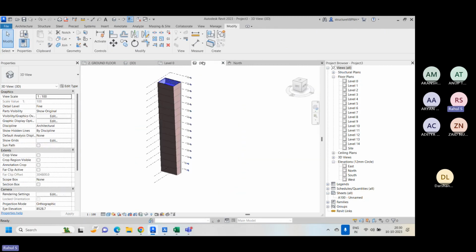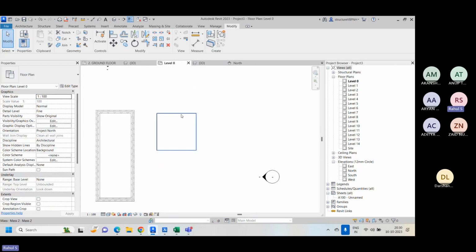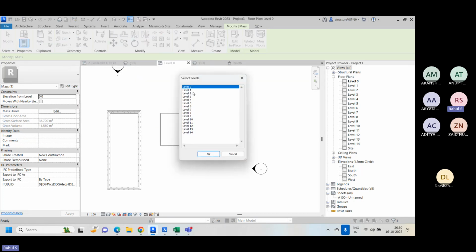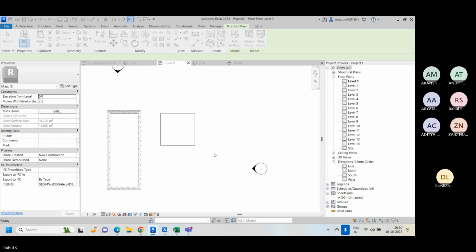So how can we give the rotation? Go to this one. Just copy, paste, align to selected all levels, and create the multiple views up to this one. So for all the levels, it will get created. Then once you set this, you need a proper rotation angle for all these geometries.